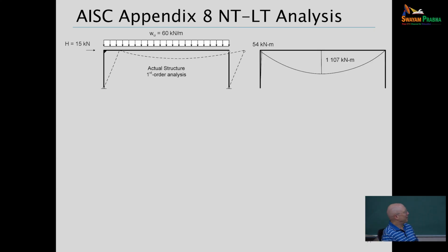Now I tell my students at Georgia Tech, if you go to Cambridge, Massachusetts to interview with LeMessurier and Associates, you may want to bone up on this frame and be ready. They might put it in front of you and ask you to explain what's going on. The one thing that maybe is important to understand is if we take away the lateral loading for a second, this frame would still have a significant side sway. Does that make sense? So why?